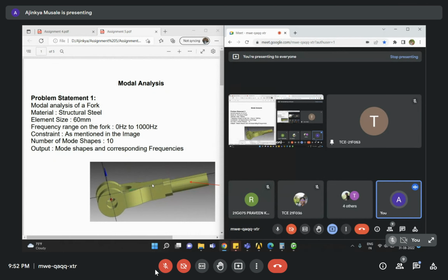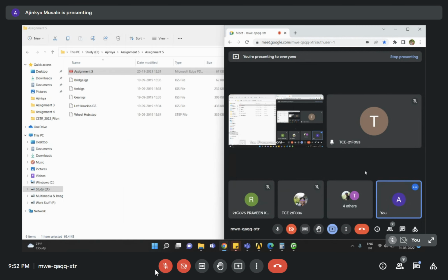In the modal analysis, we will find out the frequency, or I'll say natural frequency, and even the mode shapes. Because these mode shapes are a little bit different. These mode shapes are because of its natural frequency, or maybe I'll say a body without loading. And today what modes we have seen, they are because of my buckling loads. Fine. Okay. So anybody has any question? So tomorrow's session will be interesting, and yeah, modal calculations.